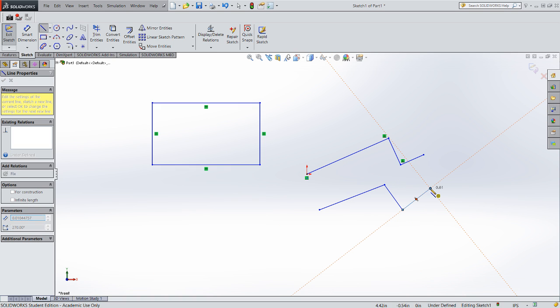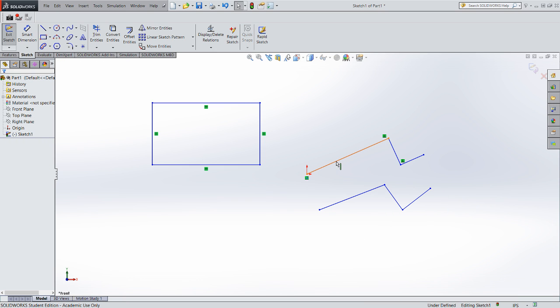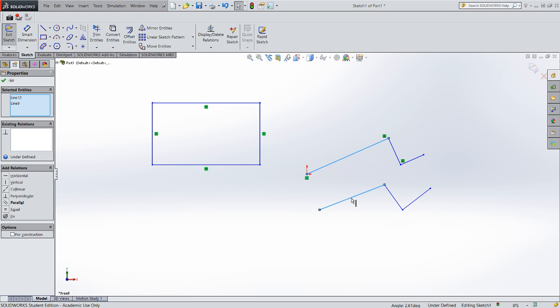But I'm not going to make it perfect. Right click, select. I can do some things to make two lines, so I'll click my first line, and then I'll click my second line, and you'll notice that over in my properties tree here, I get a bunch of properties, and I can click and make those parallel. You'll notice that I see the 4 and the 4 appear, meaning that this line is parallel to that line.